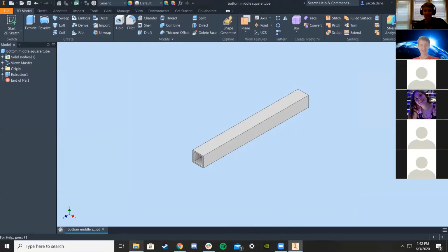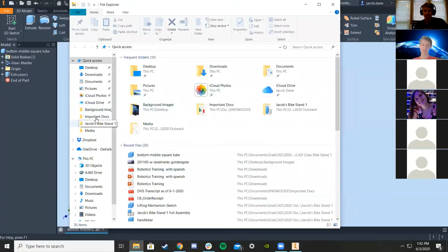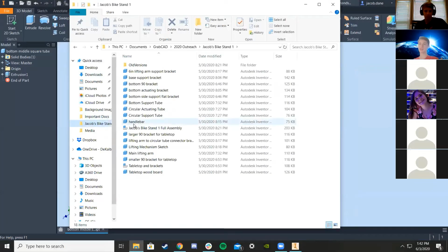Okay, and to make this easier, you have to be careful in CAD, especially when you put parts inside of assemblies, that you don't name anything the same thing that already exists. Whenever you have an assembly, it's basically taking a constraint and referencing another part that already exists. If two parts have the same name, CAD doesn't know which one to put in your assembly. So you have to make sure all your namings are correct, and when you copy pieces, you have to change those names.